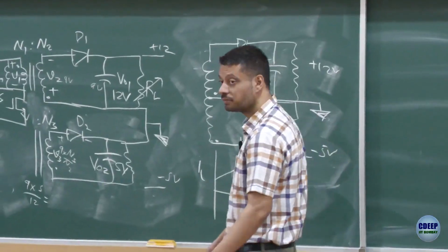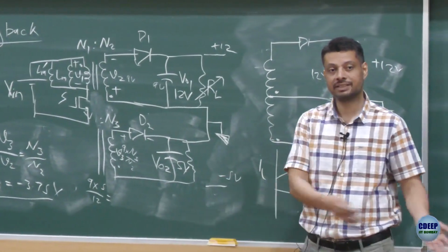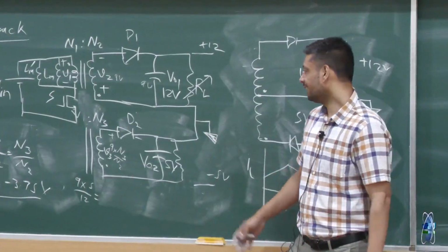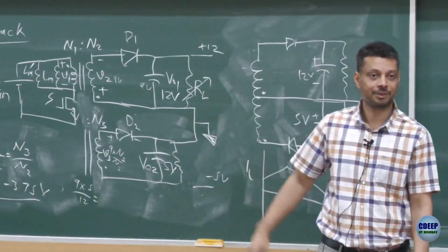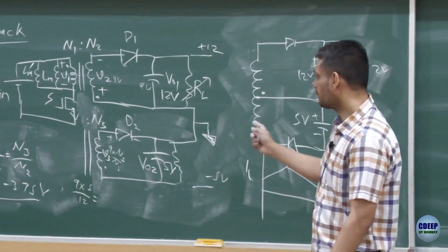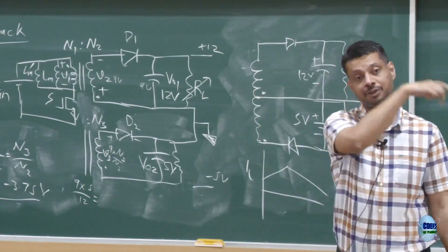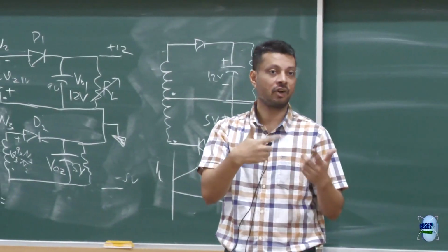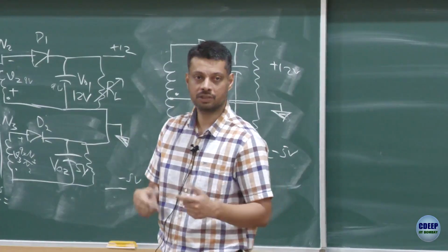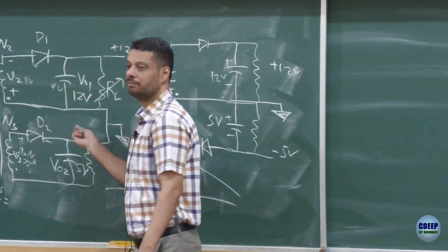So unfortunately nothing bad with the circuit then. Yeah, but here first of all you are getting an opportunity to get 2 voltages, which was not even there in the buck converter, right. So firstly you should be thankful to this circuit. Nobody is perfect, right. It is also not perfect, but still does a better job than just a buck converter. But you are absolutely correct that if one of the voltages drops, it would also have an impact on the other voltage. There is a term for it, we call it cross regulation. It is something we can see later on, or you can search for it, cross regulation, right.